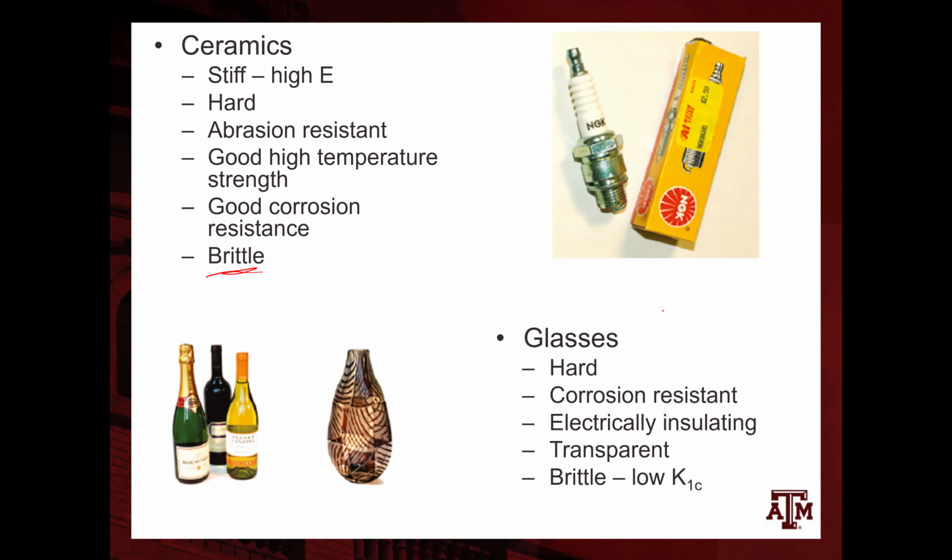And glass could also be a material having some properties that are similar to ceramics, but not all of them. A lot of glasses are amorphous as opposed to ceramics being crystalline, but they share some properties, like basically insulating in terms of electricity and heat. Also, they are, of course, much more brittle than other ceramics.